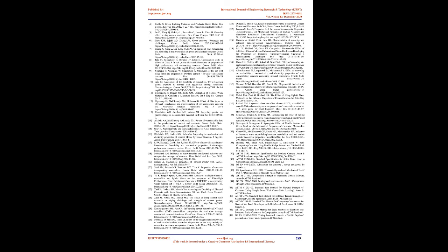The second, ranging around 415 to 475 degrees C, indicated the decomposition of CH. The third, ranging around 750 degrees C, indicated the decomposition of calcium carbonate, CaCO3, that was derived from the cement clinker 52. The first and second zones are indicators to assess the degree of hydration of the cement matrix. The CH% content of cement pastes presented in Fig 21 was obtained according to the following equation.